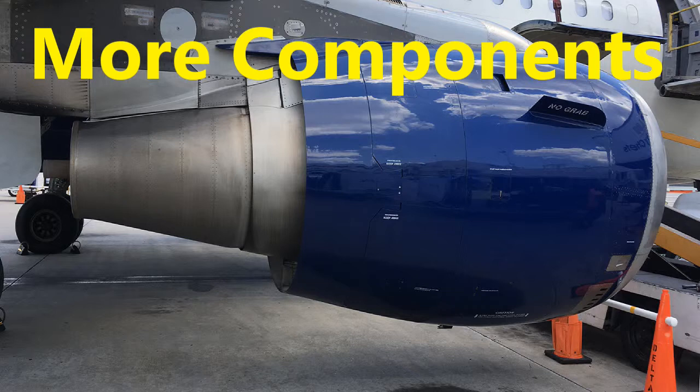And if you haven't worked on anything like this, I've talked to a lot of you, and it seems that the majority of the ones I talked to were structures people, and then there are power plant technicians. So some of you have never even worked on power plant at all, and the reason I bring that up is because in structures you're not dealing with O-rings and seals like that. With power plant, you've got all these places where you have fluid running, and every time you have fluid, you have to have seals.